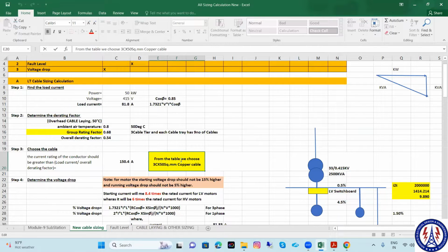Like say for example, if it is a motor feeder, then definitely there is no neutral, so R, Y, B. If it is single phase, then two core: phase and neutral. If it is a power feeder, then R, Y, B and three phase. Like that we can select. We should know the load configuration.